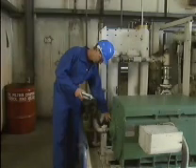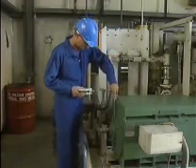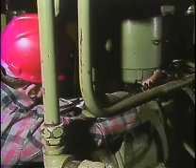Also, if possible, each bearing should be checked from 3 different directions. That's the minimum number of directions needed to completely check the vibration. For example, the bearings on this vertical shaft should be checked from an axial direction, that is, parallel to the center line of the shaft, from a radial direction, that is, perpendicular to the center line, and from a second radial direction, that is at a 90-degree angle to the first radial measurement.